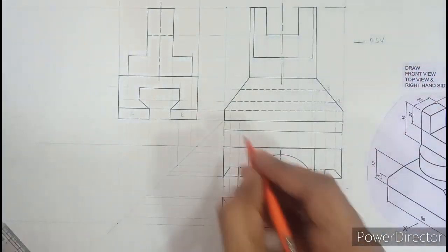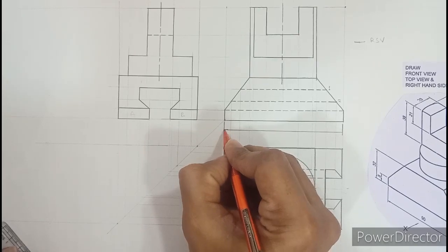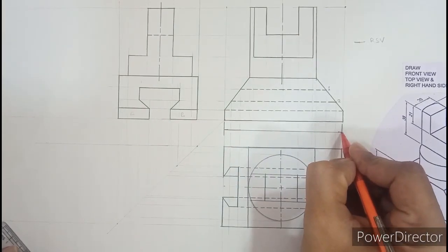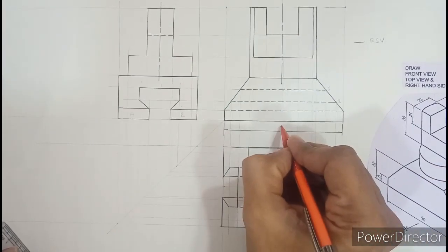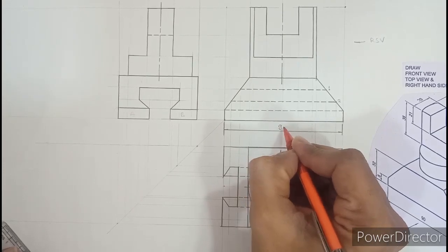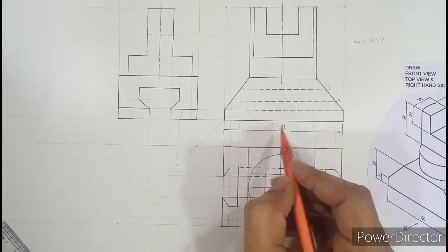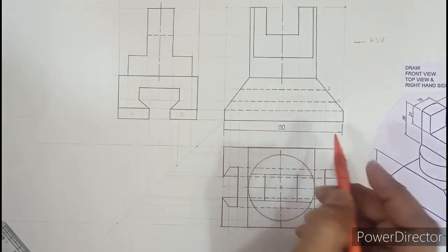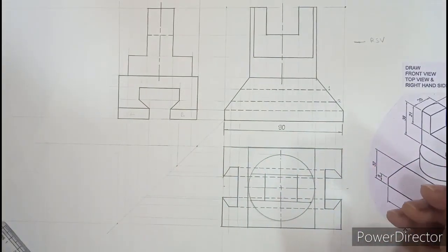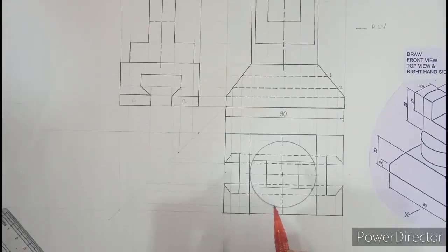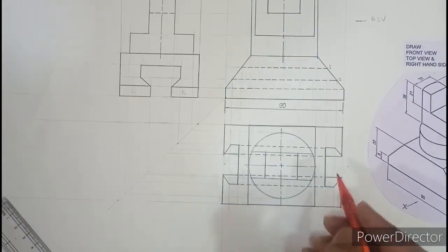the dimension line neatly. Arrow mark as thin as possible. Arrow mark is the maker. Your drawing maker is the arrow mark. It can spoil the drawing or it can make your drawing. It depends on you. So length is done. Now as I told you, for width, there are two entities, 16 and 60. So we need to spread the dimension in all the views. All of you know that.